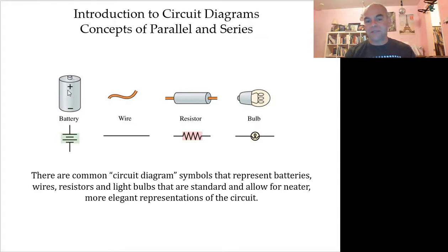And you'll see pictures that have these symbols on them to show the different things that we want to talk about. For instance, a battery, which looks something like this if it's a AA battery, is represented by a vertical line here, a vertical line there, and then these other parallel lines of different lengths. They actually represent how a battery is built, because the battery is often built with layers of different materials stacked upon one another, and that's what that symbol represents. It could also be turned on its side. I should note too that a battery isn't always vertically oriented, it could be horizontal.